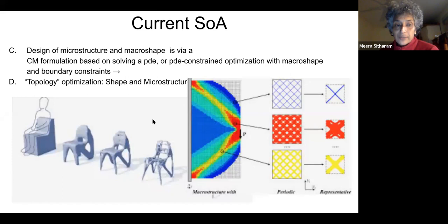So now that you have the ability to make very fine things, print really tiny microstructures and design them to enormous precision, what you do is you design your microstructure and the shape together. It's a common process, with lots of software tools now, called topology optimization. It has an external boundary constraint, both on shape and loading. Again, I'm using loading in a very general way, as though it's mass and force, but it could be electrostatic properties, magnetostatic properties, and you could even go into dynamical properties. I won't emphasize that.